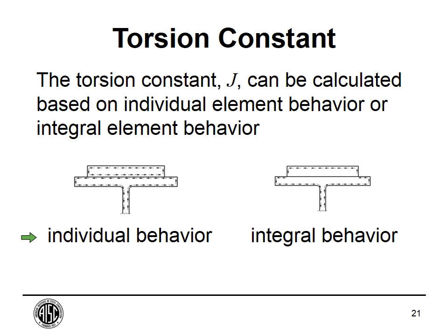And if you remember from way back in Strengths of Materials course, if you have torsion, and we're talking about St. Venant torsion here, not warping torsion, your maximum shear stress on the cross-section is going to be on the outside edge, like I've got shown here. It goes around the outside edge of the wide flange section. And because we're twisting independently, we treat the plate independently too. So the shear stress is going to go around the outside of that plate.